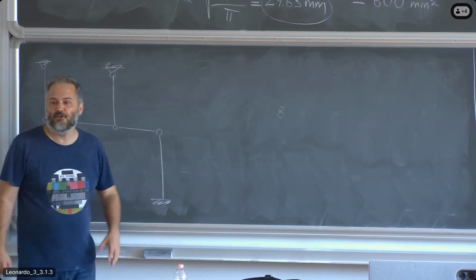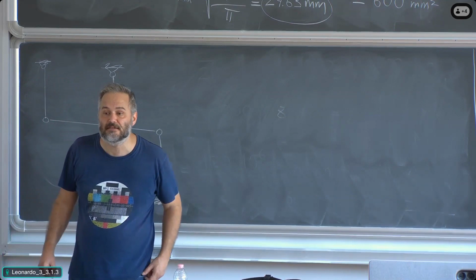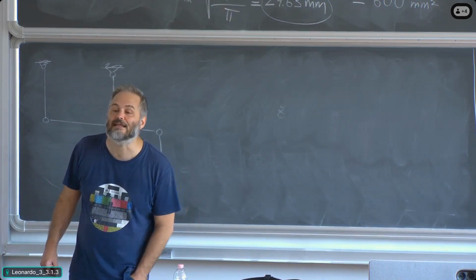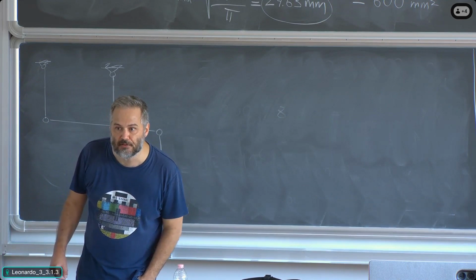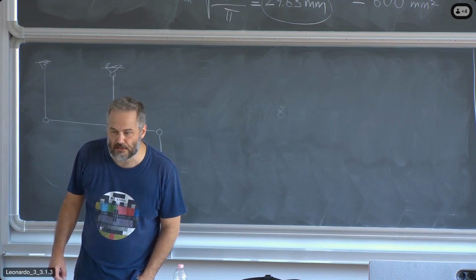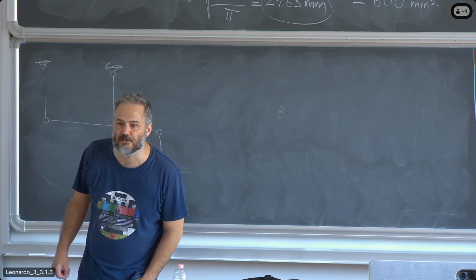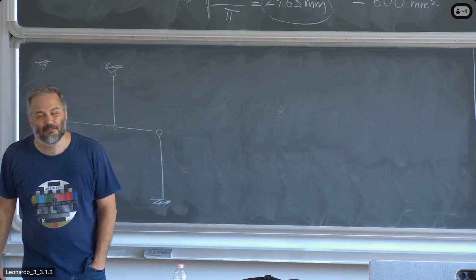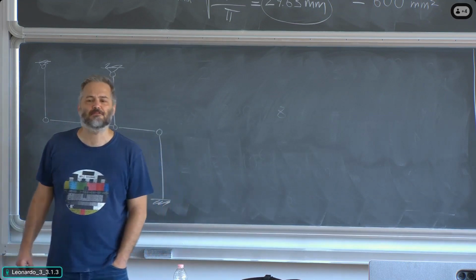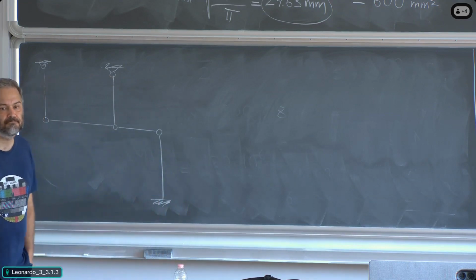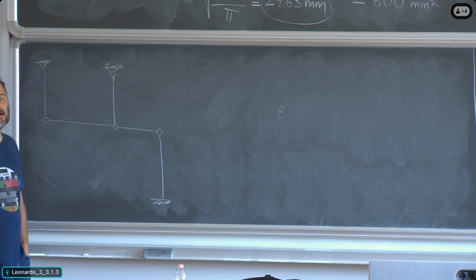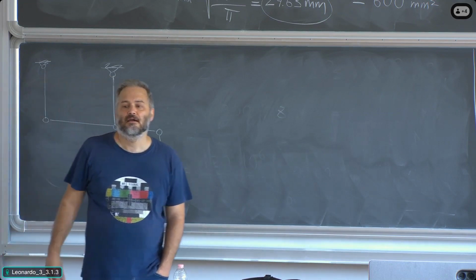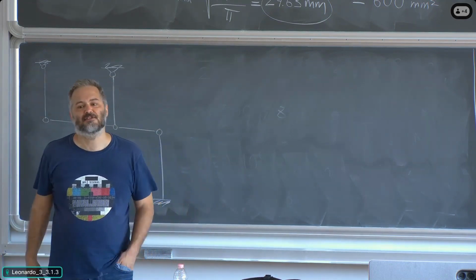As regards the top, the question is, can it rotate? It can clearly rotate because there is a hinge. So the top of the column is free to rotate. No restraint as regards rotation. The more complex question is, can it displace? Apparently, some may think it is restrained by the rest of the structure.